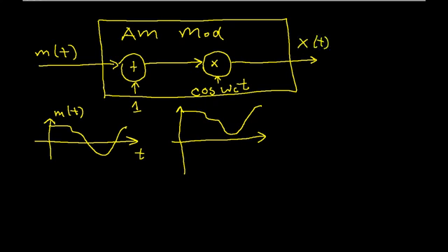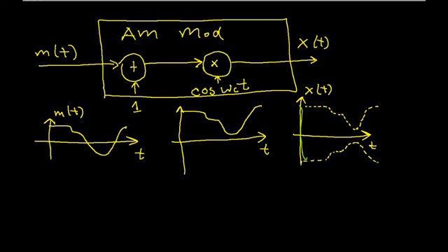And this signal then goes through a very large power amplifier and is broadcast through the antenna. So if we look at what x(t) looks like in the time domain, it basically has an envelope given by the raised up m(t). And so I'll draw that envelope. And x(t) wiggles between the two levels of this envelope. So you can see that the amplitude of the cosine waveform now depends on m, and that's why we call it amplitude modulation.